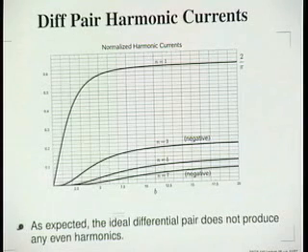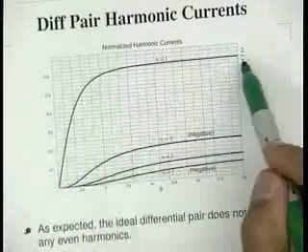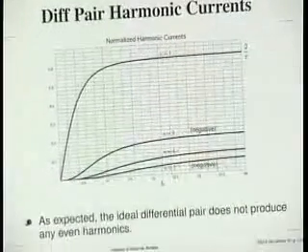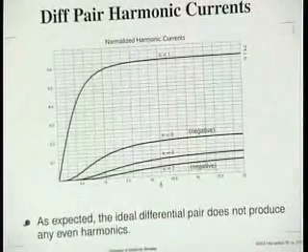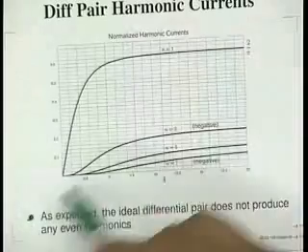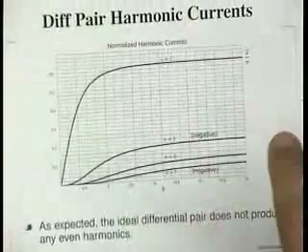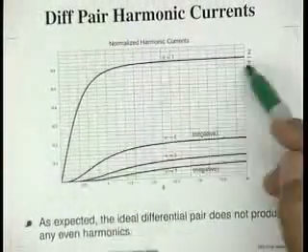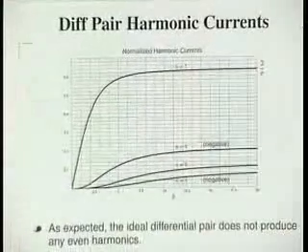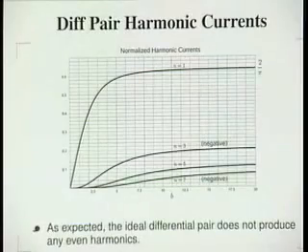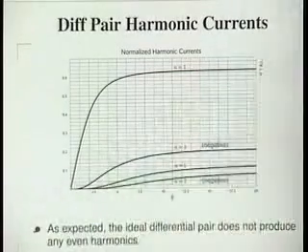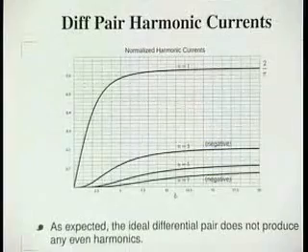Now here we can see that the bias current naturally limits. That's because this waveform here naturally limits, and the reason is there's only current IEE. IC1 can never get bigger than IEE, so there's a natural limiting mechanism. In the bipolar amplifier, the limiting mechanism is due to the fact that we somehow force the bias current to be constant. If we don't force the bias currents to be constant, then you'd find that the current just increases without bound. Okay?